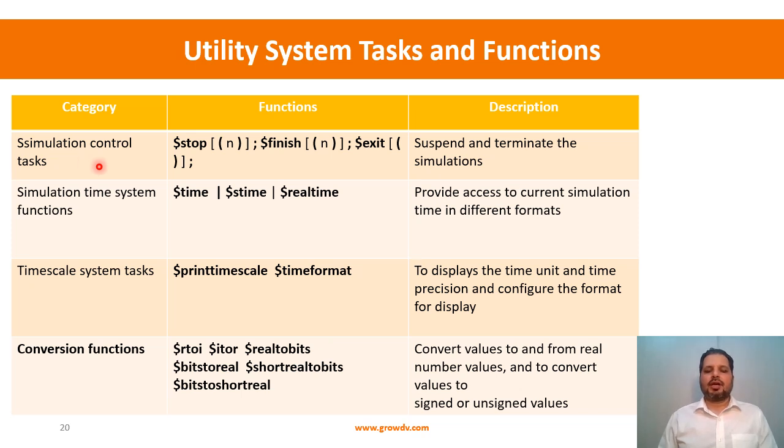So we have the simulation control task category, wherein, for example, we have been using $finish, and we have used $exit in error cases, and then you also have $stop. I think in the bootstrap verification with Verilog, we had used all three of them. So you can use these for either suspending or terminating the simulation.